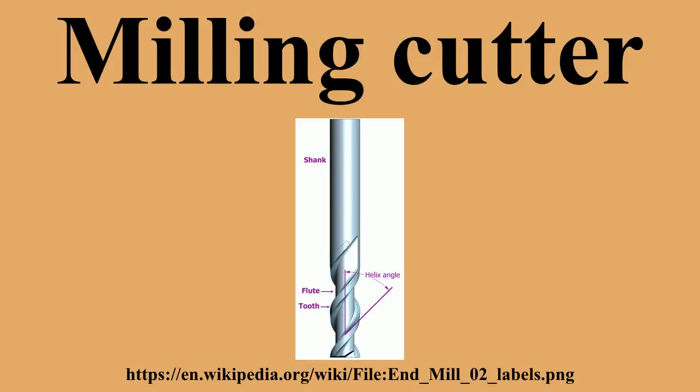Face mill. A face mill is a cutter designed for facing as opposed to, e.g., creating a pocket. The cutting edges of face mills are always located along its sides. As such, it must always cut in a horizontal direction at a given depth coming from outside the stock. Multiple teeth distribute the chip load, and since the teeth are normally disposable carbide inserts, this combination allows for very large and efficient face milling.